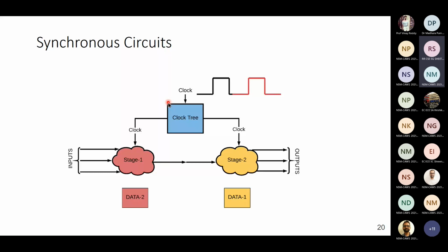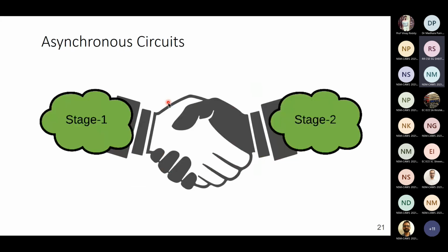When I say clock tree, we have to bring in the clock tree because it's not at the Verilog level. So we have to synthesize it, then lay it out, and then do what is called post layout synthesis, and then this Verilog code is extracted. If you have any questions, or if you want to know more about it, we can discuss once I'm done with this.